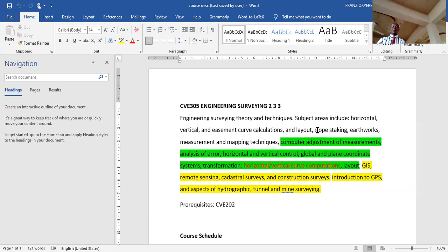So we do some coordinate transformation, so that you appreciate that there are different types of coordinates. We can have coordinates that are global, like national. And there are coordinates that are just local to the project. Once we agree there are different types of coordinates, but it's the same place I'm working on, what I'm saying is that it means we can do a conversion.